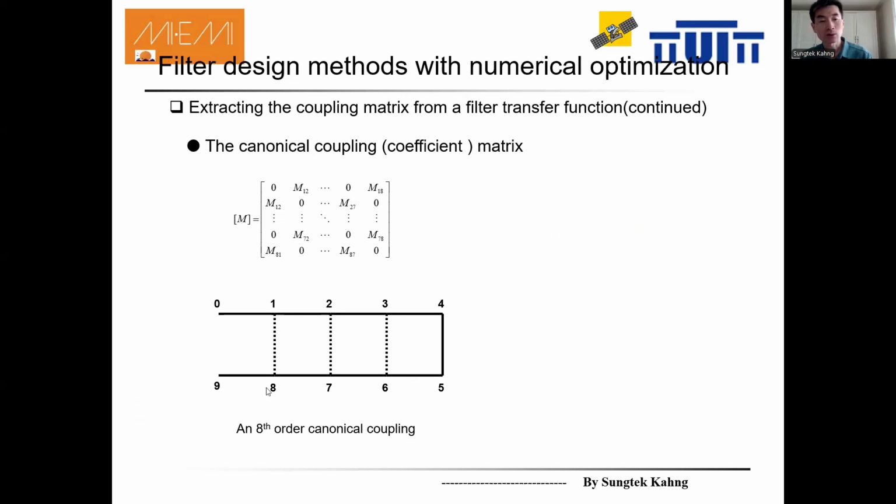1, 2, 3, 4, 5, 6, 7, 8. These numbers mean the numbers of resonators, so resonator one all the way down to eight. From one to two, this is called sequential coupling. The way it flows, it is called a sequential coupling. Between the nodes are resonators. These are coupling coefficients. You will give M12 here, and M23 here, and M34 here.